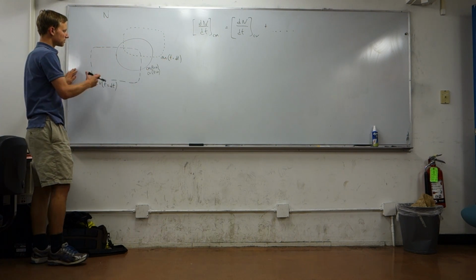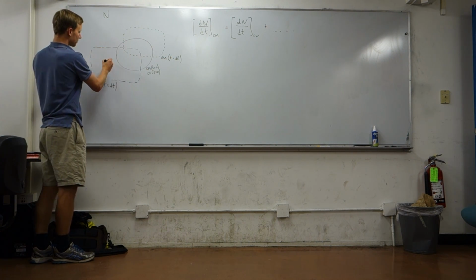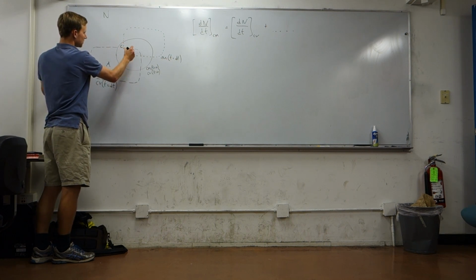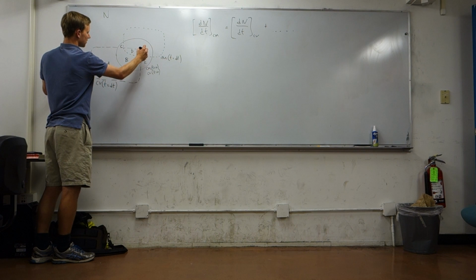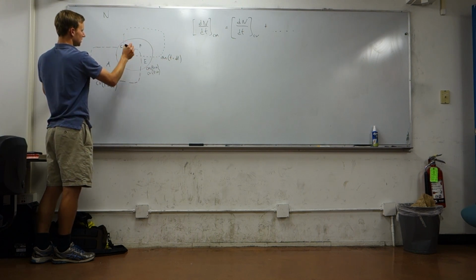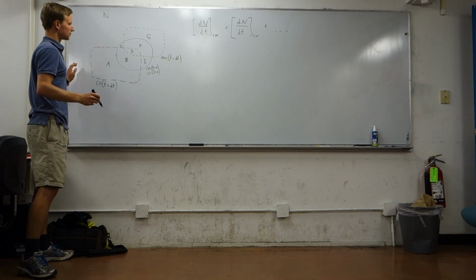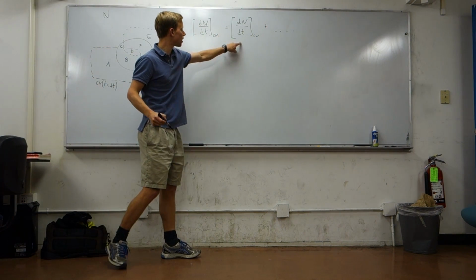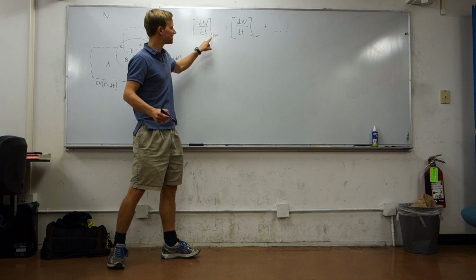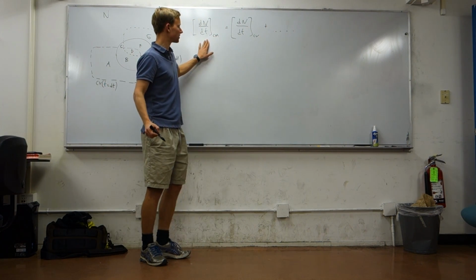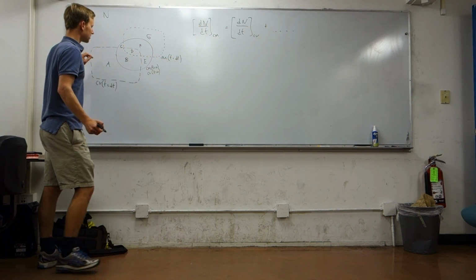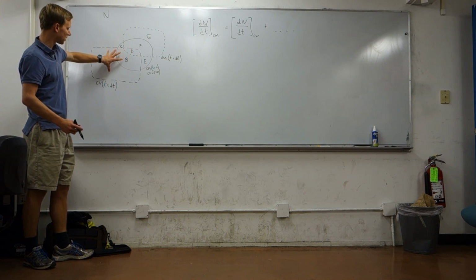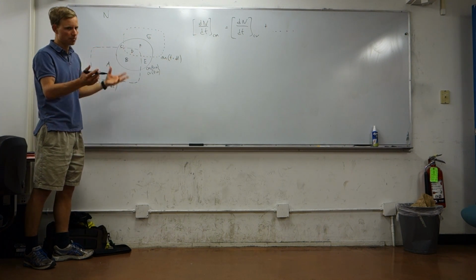Let's think about this in terms of volumes of stuff. And since this is a 2D problem, we're going to do this in terms of areas. So I'm going to label these areas with letters: A, B, C, D, E, F, and G. We're going to express these two quantities out. We want to relate them and see what's going to be required to cause this relationship to hold. So dn/dt in our control mass is the stuff in our control mass at time t equals dt minus the stuff in our control mass at time t equals 0, divided by the time increment.